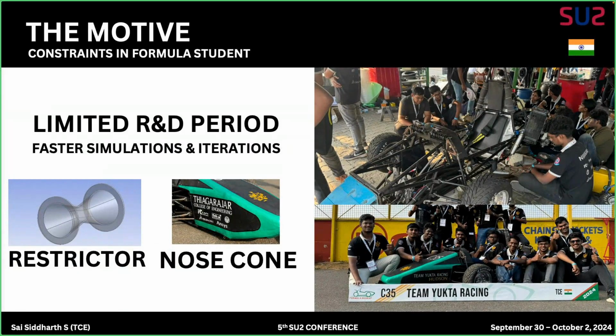Initially, I used radial basis functions for mesh deformation, which is a standard approach, as we all know, for aerodynamic shape optimization. However, while I was designing the nose cone for the Formula Student car, I was working on a side project, let's say, in parallel with the car. That is when I started questioning whether different techniques would improve meshing, offer more localization, or enhance smoothness. This led me to explore NURBS, the non-uniform rational B-splines.